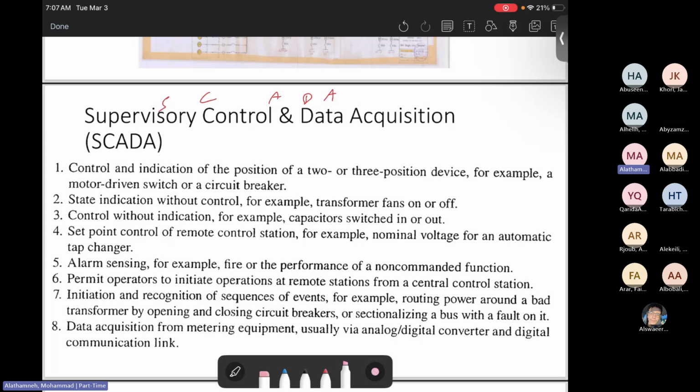Our own network is used to transfer the data from the substations to the control room and to control the circuit breakers and the rest from the control room. It's not using the internet network. So we can avoid cyber attacks and any problems that come from outside. Therefore, by isolating this, we can guarantee there will be no outside disturbance, no outside hackers.